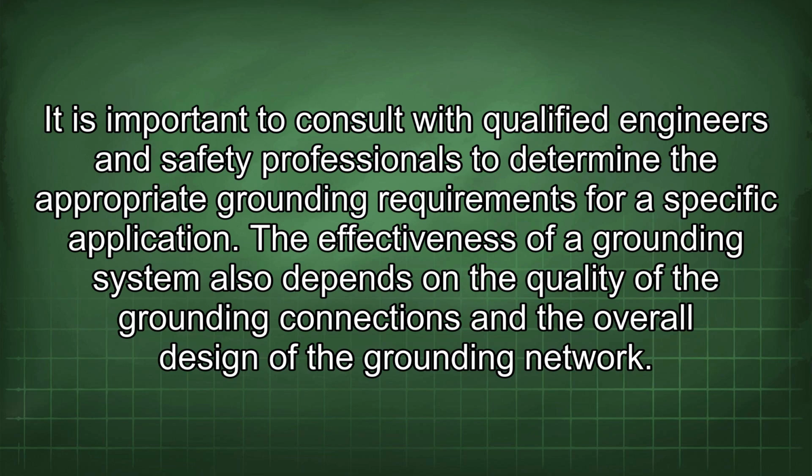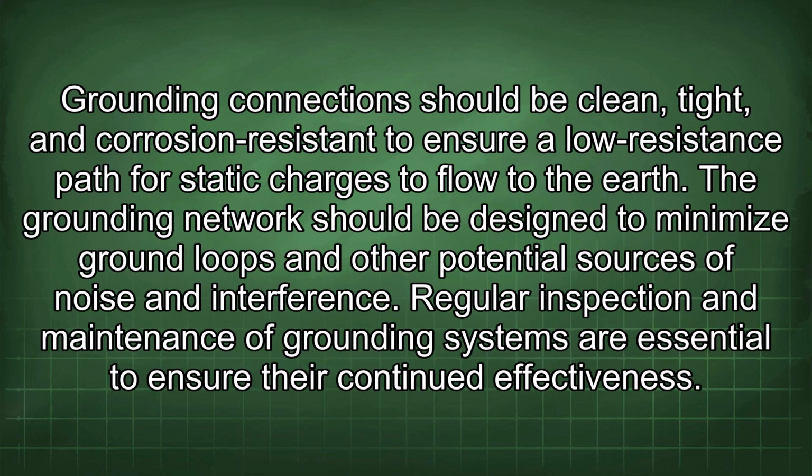application. The effectiveness of a grounding system also depends on the quality of the grounding connections and the overall design of the grounding network. Grounding connections should be clean, tight, and corrosion resistant to ensure a low resistance path for static charges to flow to the earth. The grounding network should be designed to minimize ground loops and other potential sources of noise and interference.